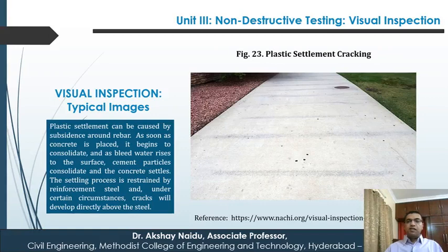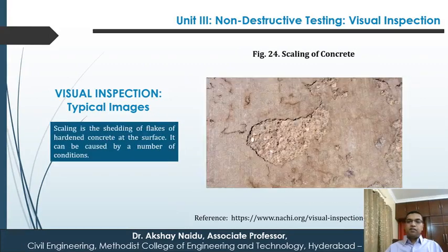Then of course plastic settlement cracks. As we know, concrete settles in the fresh state, and if reinforcements are obstructing, then right above the reinforcements the concrete which is beginning to set splits and forms cracks like this, a parallel crack pattern.